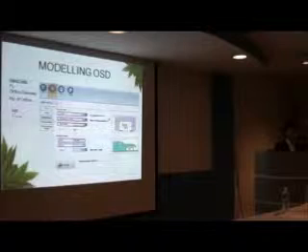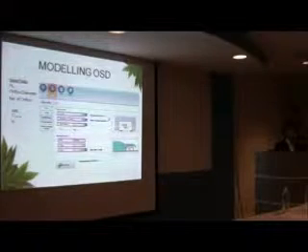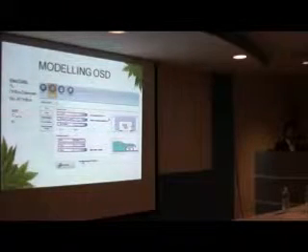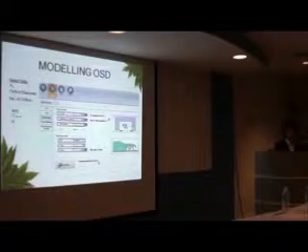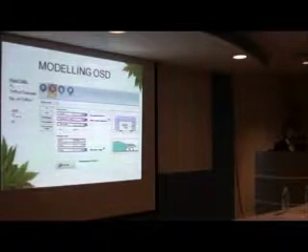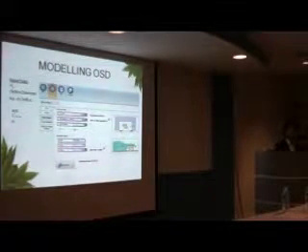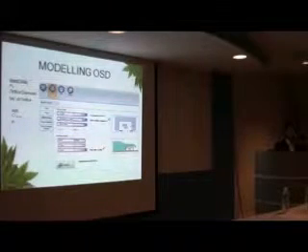And then the broad crested weir coefficient, and then the H, the overflow height, and then the program will give the required storage. This is the required storage. The program will automatically propose the weir width. The weir width is perpendicular to this diagram.